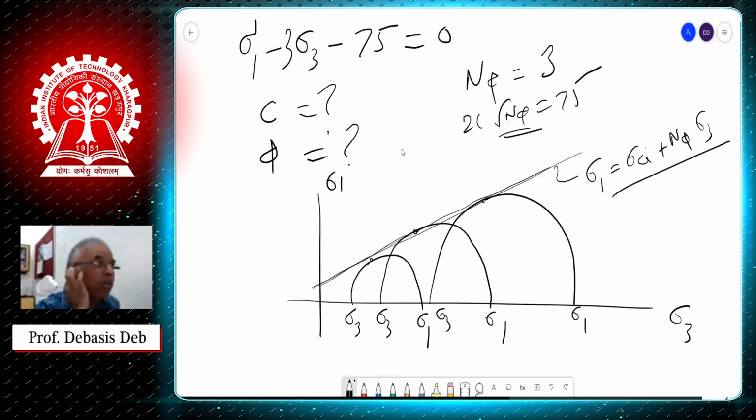So when I say a series of triaxial tests, I mean that they have done at least 3 or 4 triaxial tests by varying the sigma 3 and they found different sigma 1, and then they plot a common tangent. As I'm telling you, finding a common tangent is a very difficult task. And then we plot the straight line of that common tangent, and that is the equation given here.